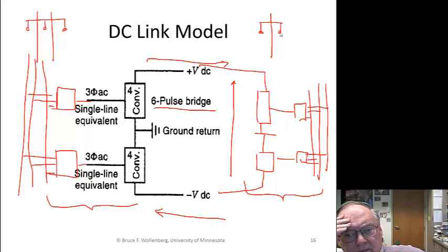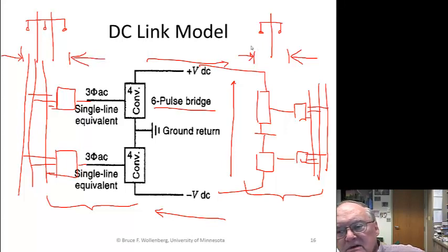It's only got 1 pole, and the way I built it there, and the so-called right-of-way that I need, this width of land that I need for the DC line is much less than the land width that I need for the AC line. So I don't have to buy as much land for the DC line. So it's cheaper.